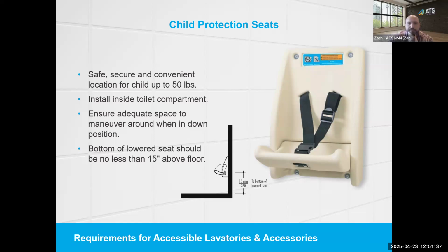But there's nothing in there that I'm aware of that talks about children's lavatory or children's countertop height. But I've seen restrooms for preschool, and I've seen toilets and toilet compartments where everything is lowered. So if you're lowering the lavatory, which I'm sure you would, then I would say if you put the mirror within about 6 inches of whatever height you establish for the countertop or lavatory, that would probably work.